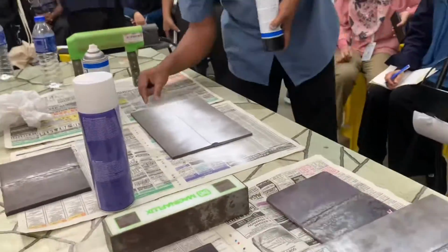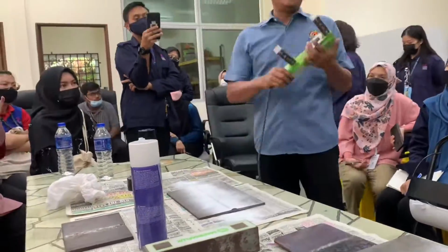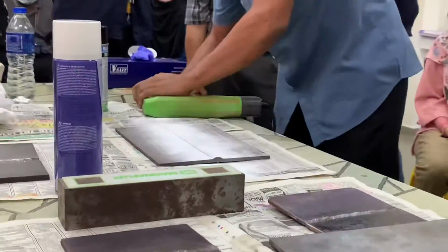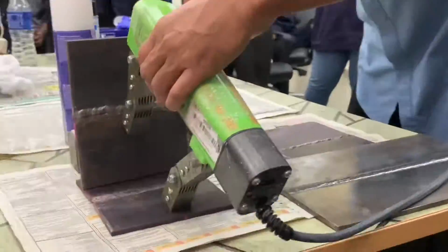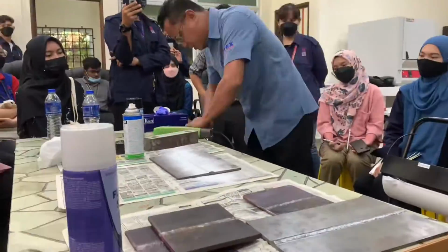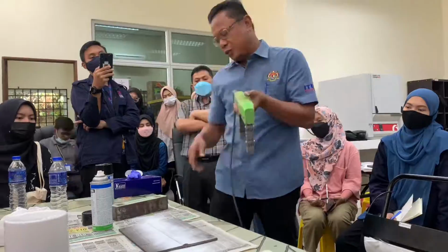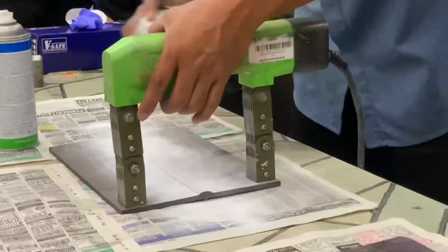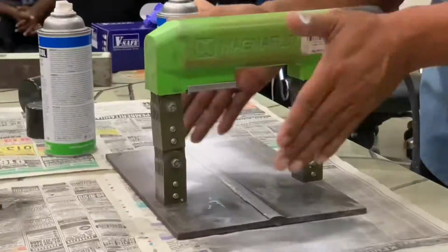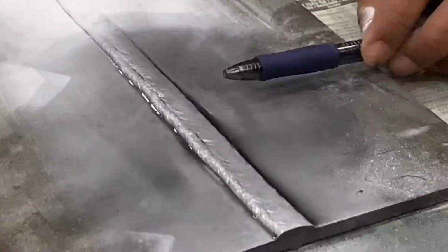So there are several methods. The most adaptable method is to use a 110 volt AC handheld electromagnetic yoke magnet, a white strippable paint as a contrast background, and a magnetic ink made of iron powder particles in a liquid carrier foundation. The area is magnetized with the yoke magnet. In the event a surface or slightly subsurface defect is present, the lines of magnetic force will deform around the defect.